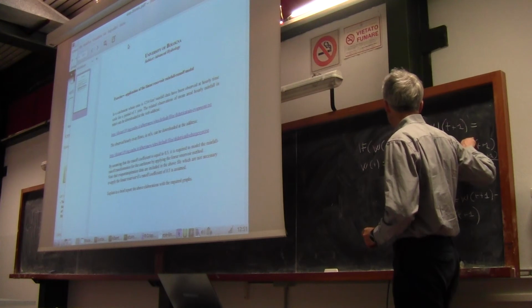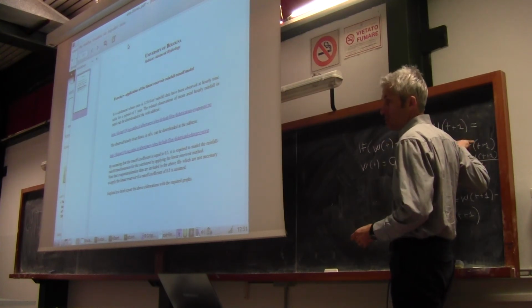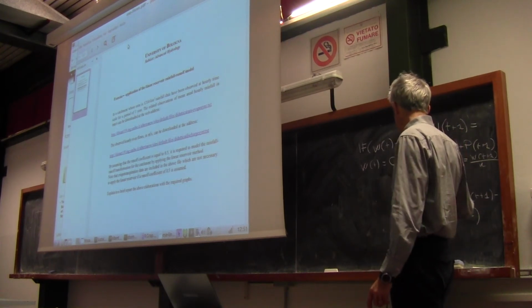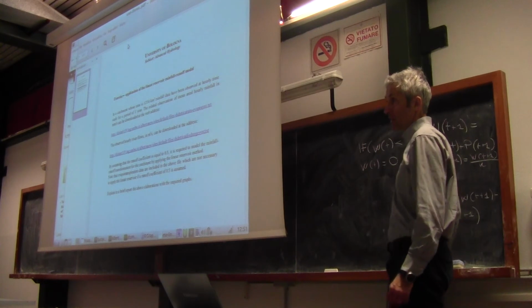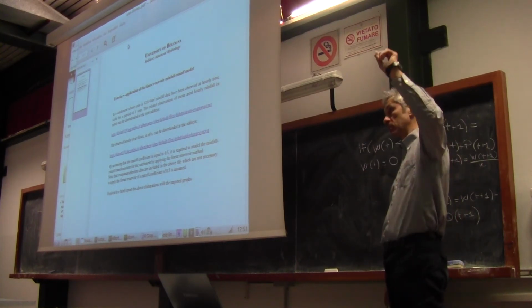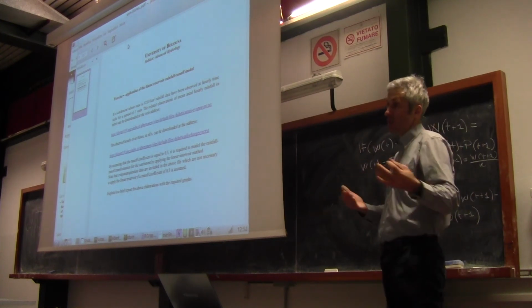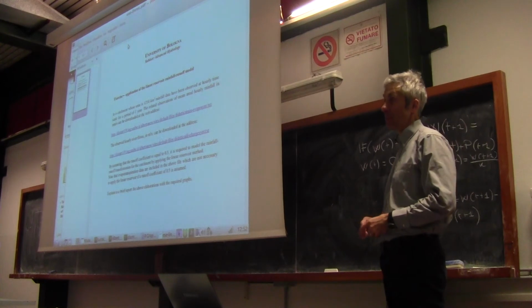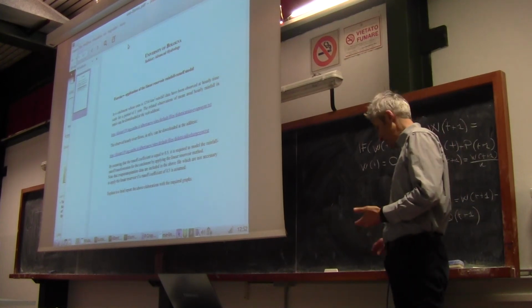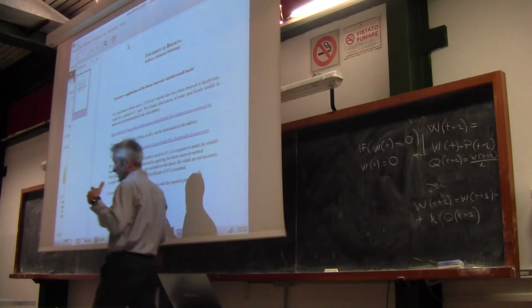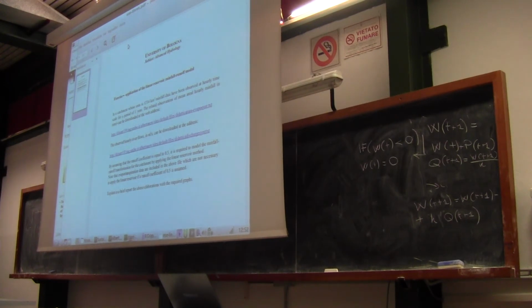Of course, here I didn't put the runoff coefficient of 0.5. You need to multiply rainfall times 0.5. And you can see what happens if you play with the k value. The k value is defined at the beginning in your program, in your code, like k equal to 50,000. You can reduce k to 20,000 and see what happens. It's very interesting. And then, if you want, you can make some considerations. What is k? What happens if I put a k that is smaller? What happens if I put a k that is larger?